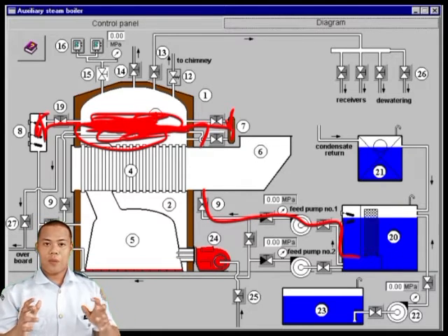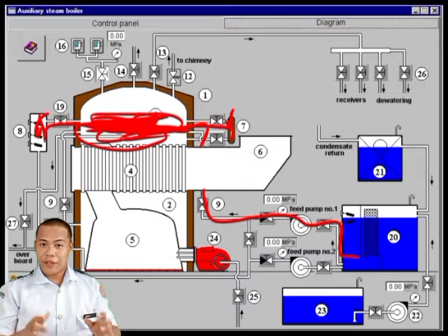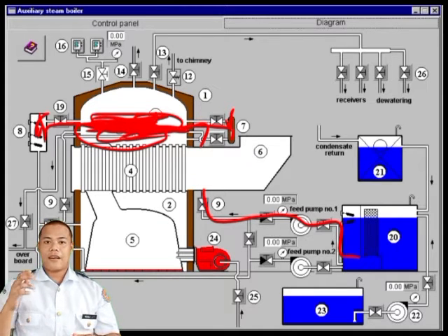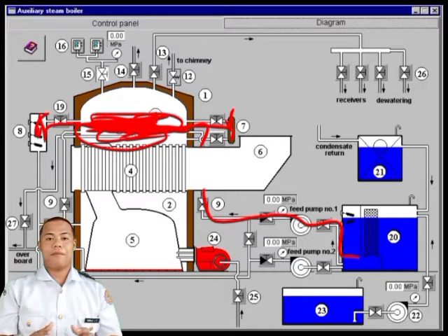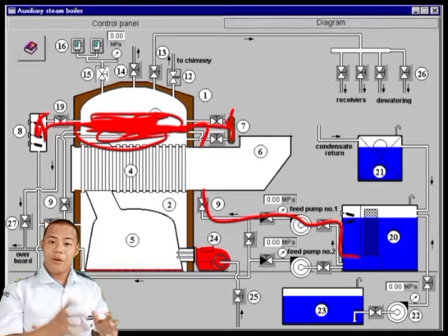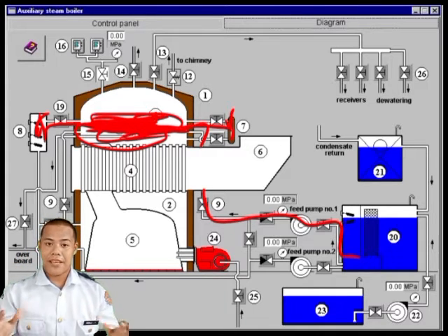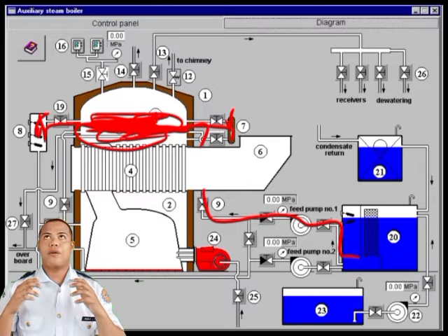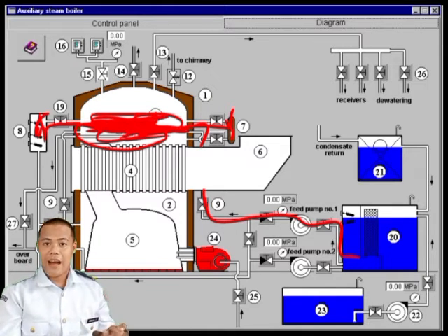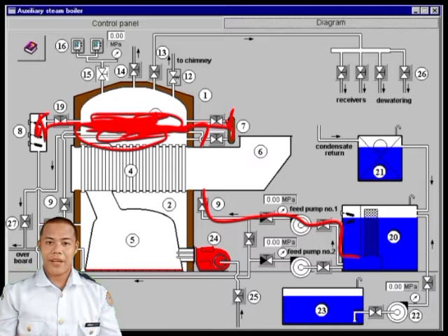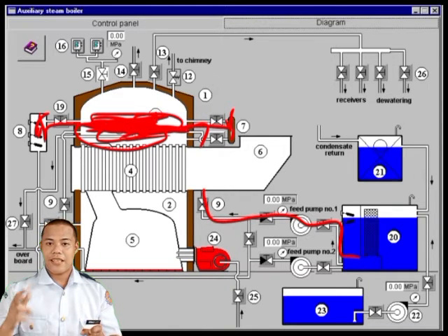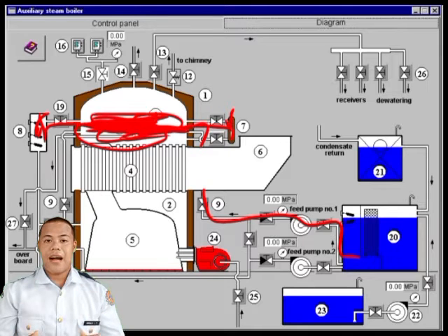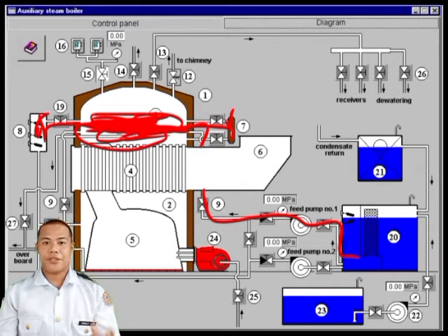And once the water inside the boiler reaches 45 to 50%, that can be seen in the water level gauge, then stop the feed pump of feed water into the boiler so that the steam will have a space for expansion, and to prevent also water priming, that is water carried out into the steam line, and also to prevent water hammering that may cause damage and also decrease the efficiency of our steam as it is heated up later in the operation.